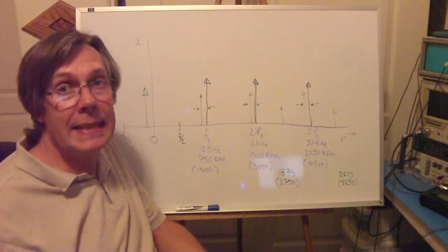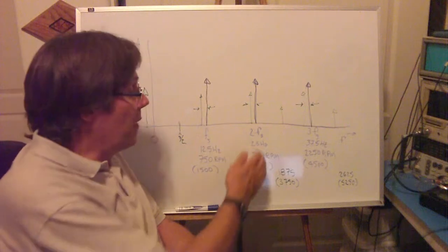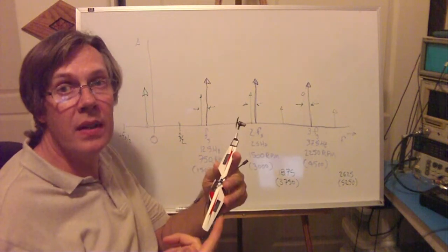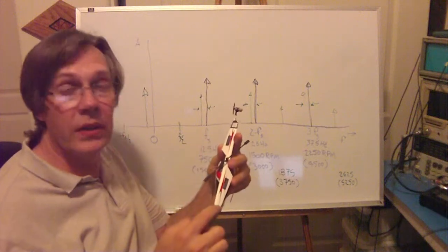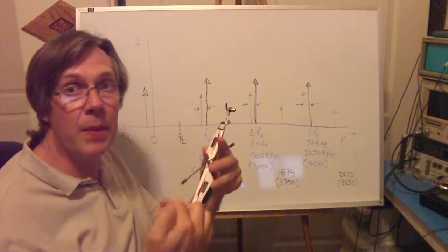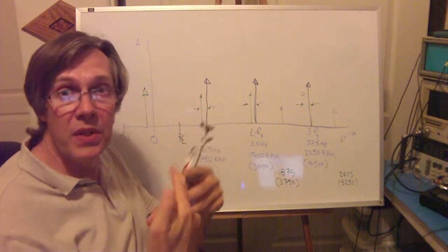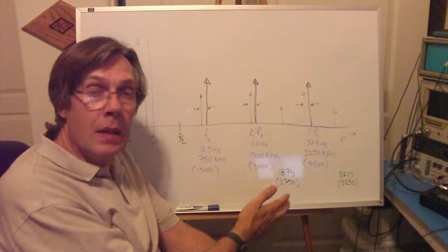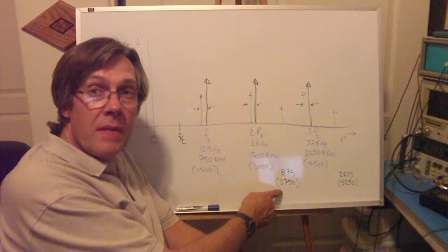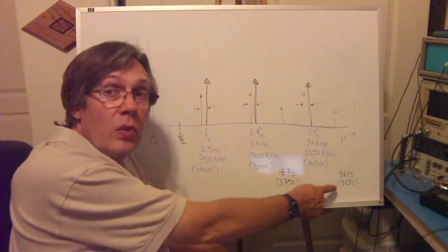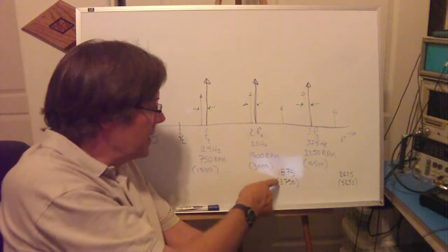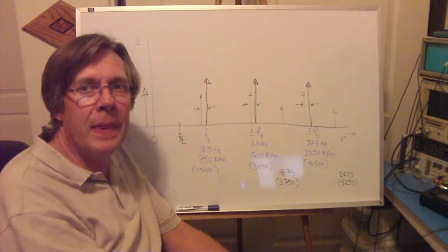We also saw exactly as we predicted that halfway in between those, where we had an integer plus a half rotation, it looked like we had a reflector on each blade because every other sample, the reflector would be on the other position. We saw those exactly where we expected and predicted to see them, which was at indicated 3750 and indicated 5250, which is double the actual rate that it was turning, really 2625 and 1875 RPM.